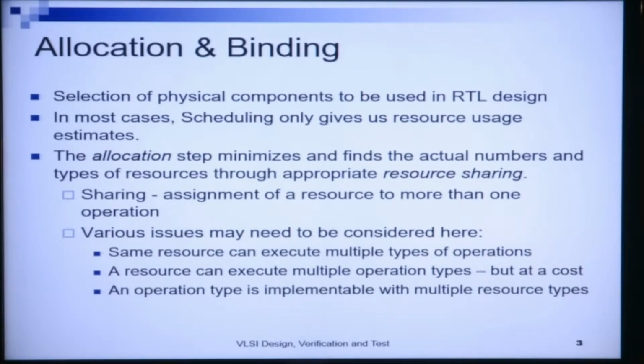Now, when we do resource sharing, we need to keep various issues in mind. For example, let us consider the case of functional units. The same functional unit can execute multiple types of operations. In the scheduling step, we saw that the comparison operation, the plus operation and the minus operation were all being performed using the ALU.